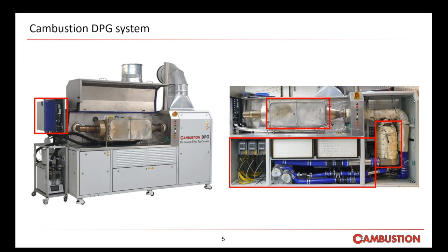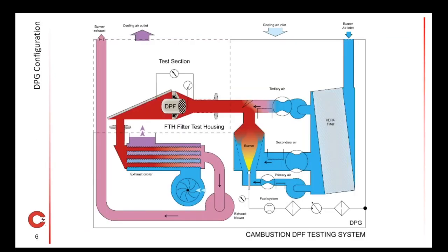Here's just another schematic of the DPG. The principle of it is the airflow is actually sucked through the DPF or GPF. There are two main benefits of this. The entire air system is then below ambient pressure, so potentially poisonous gas leaks are inwards, not outwards, to the environment. The soot generator is also less affected by the buildup of back pressure across the filter. The vacuum is created downstream of the filter, leaving the upstream burner relatively stable, close to ambient conditions.